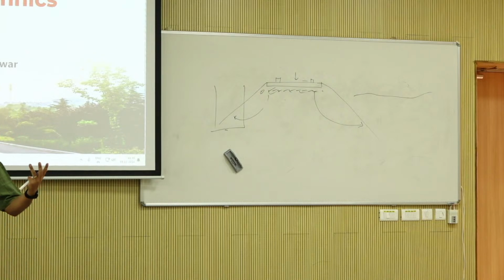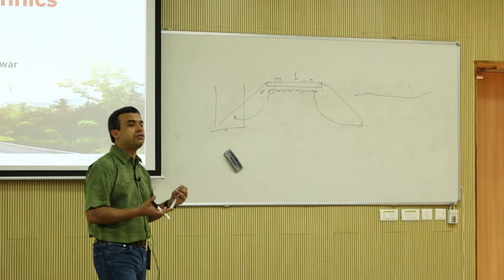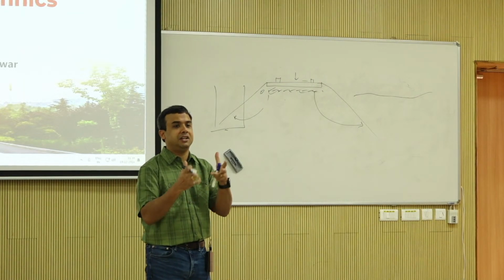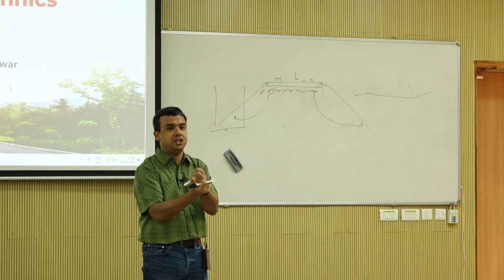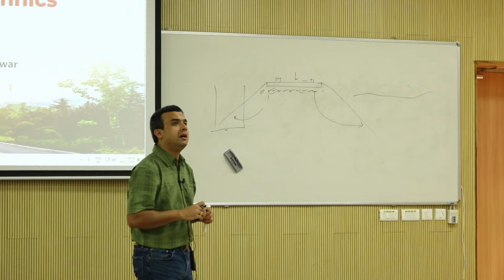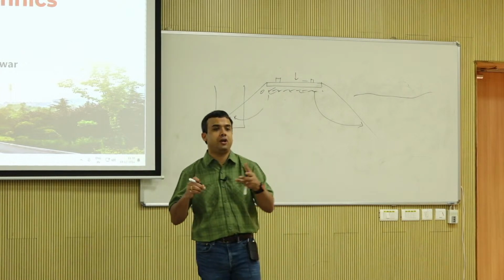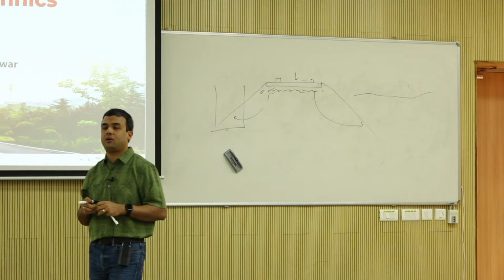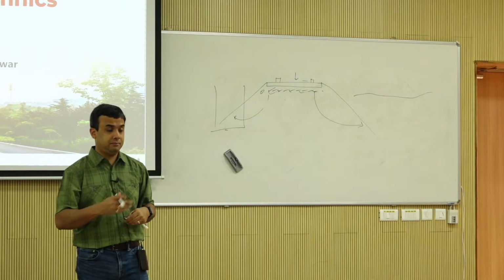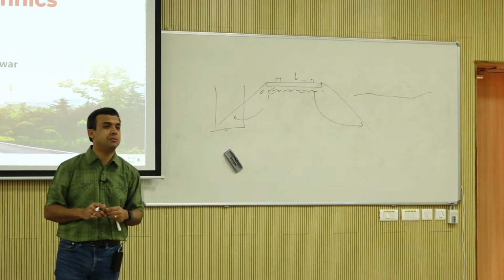There is an abundance of wood, and it's more absorbing. It's not as rigid. It doesn't degrade the ballast very badly. But when you go to higher speed, higher demand, like the Northeast Corridor, where Amtrak runs a lot of the passenger service, there are a lot of concrete ties, but a lot of timber as well.